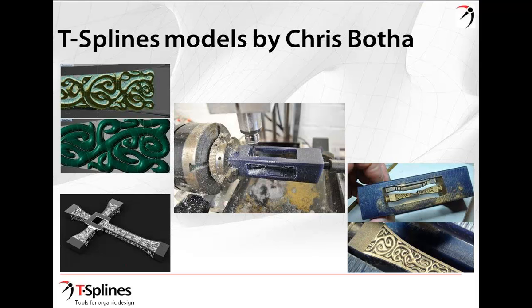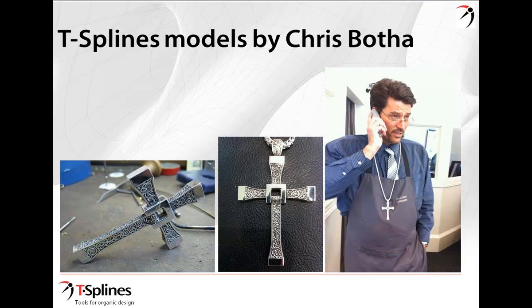I have had this conversation with so many people on the 3D CAD forum and actually outside of it. You use a hammer to hammer nails and use a screwdriver to drive screws. Don't mix the tools up. The tendency to grab a new tool and try to use it for everything will trip you up. I was trying to make shanks, and I was trying to do all kinds of stuff using T-splines where just a curve and a profile and sweeping would have been so much faster. So the tendency to try to use T-splines for everything, and when it doesn't work, give you a negative impression of the tool, can be really bad. Use Rhino for what it's good for, and use T-splines for what it's good for, is what I find.